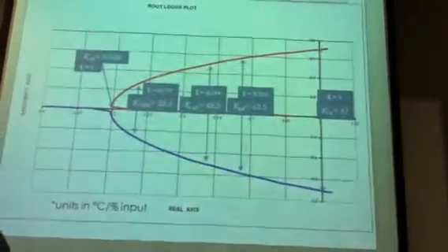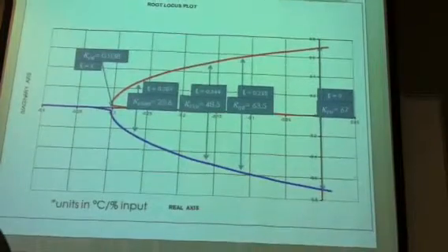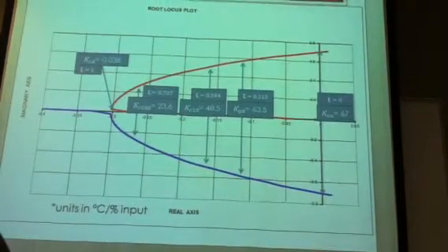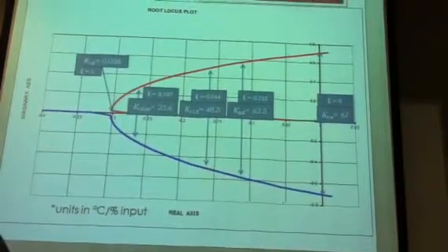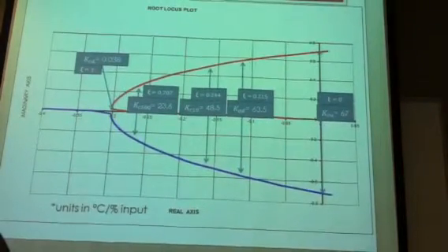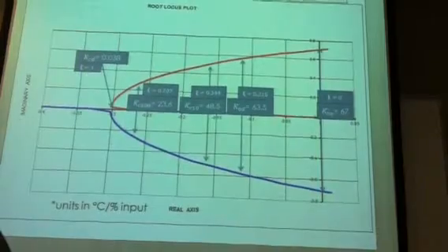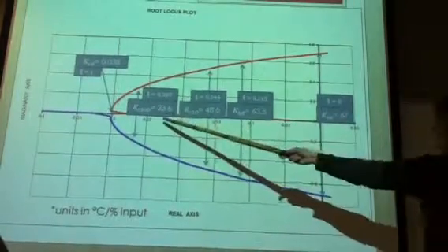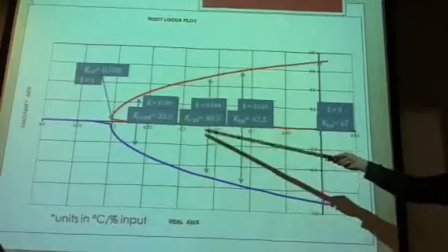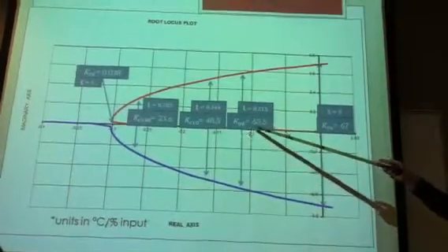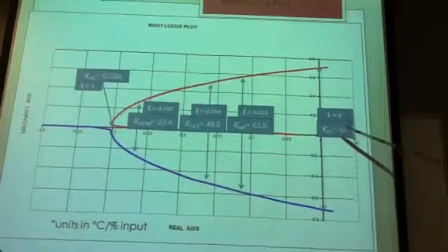This is our Root-locus plot, and you can see where the zetas vary according to the KC values. 1/10 decay occurs here, 1/500th decay occurs here, and this is the KC value for 1/500th decay, 1/10th decay, quarter decay. This is the ultimate controller gain, where zeta is 0.